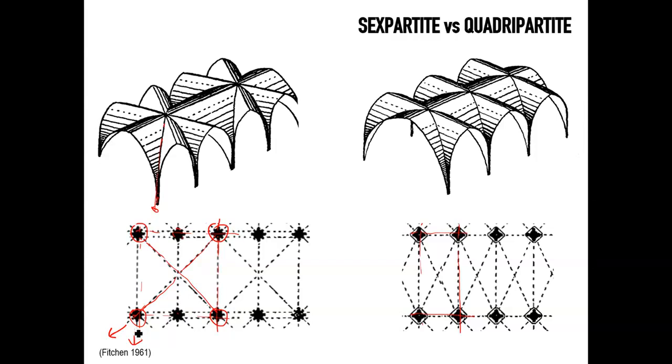The component of lateral force here is something that could be picked up by the buttresses. But if you're building a cathedral, normally you would go bay by bay, it's almost modular construction. Whereas you might build piers and side buttresses that will be able to absorb this thrust, the thrust from this side of the cathedral is not going to be absorbed until the next bay is built.